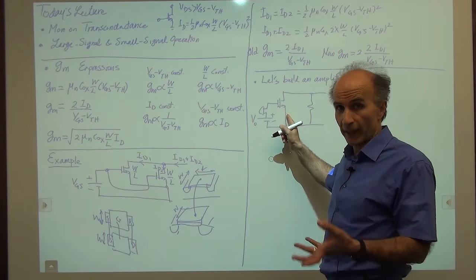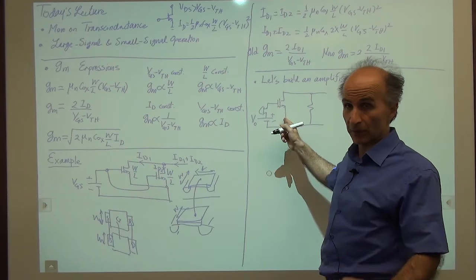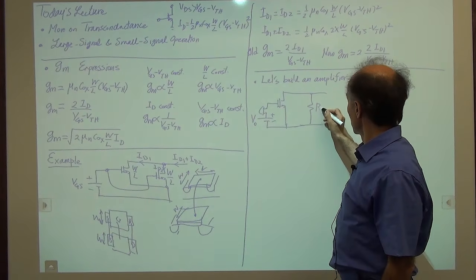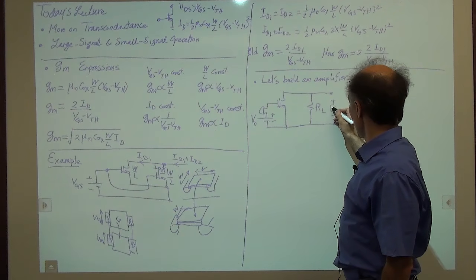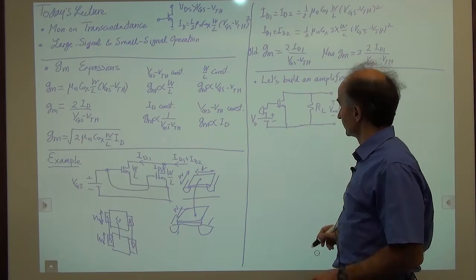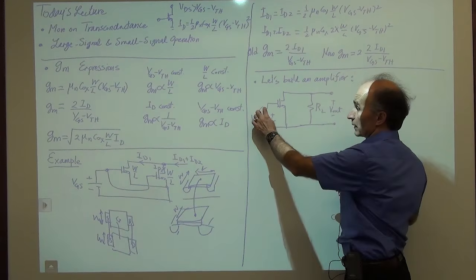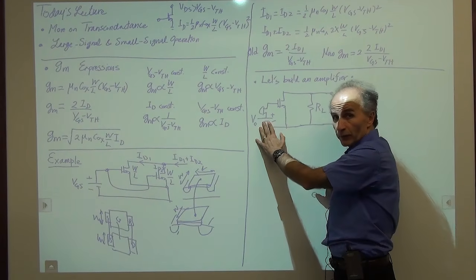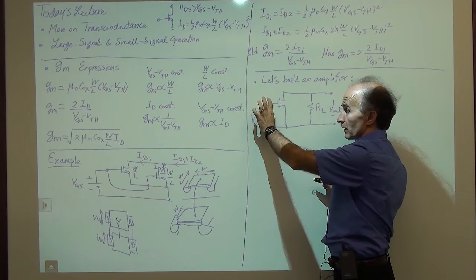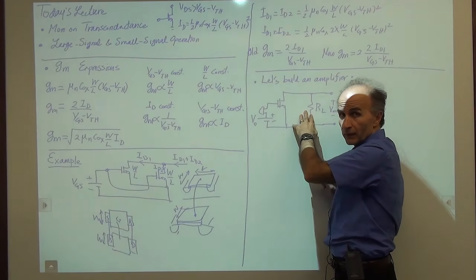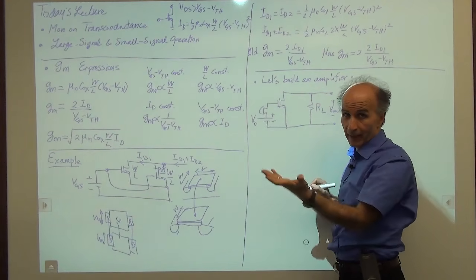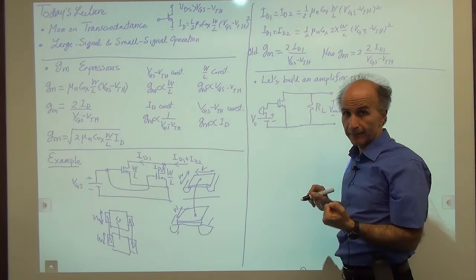We usually like voltages as outputs and maybe even inputs. So we pass it through a resistor. And we said, this is our output voltage. So if the microphone signal is superimposed on a voltage, when the microphone signal changes, it wiggles, this current changes, the changing current flows to this resistor, this voltage changes, and that's the amplified microphone signal.